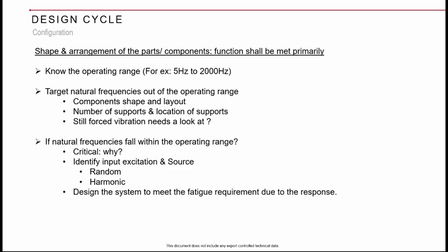What happens if your natural frequency falls within the operating range? That is critical. Why is that so critical? We already discussed that, so in the interest of time I want to skip that question. It is a resonant condition, and the response can be significantly high, and your system can fail if it is not adequately designed for fatigue requirements.